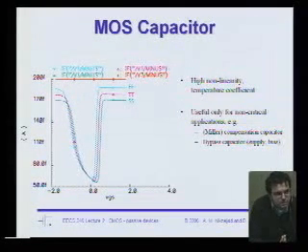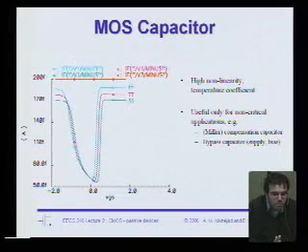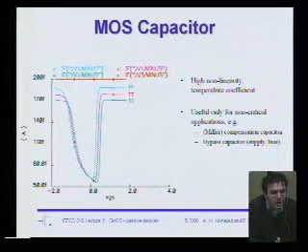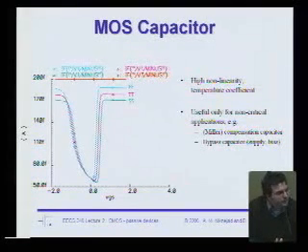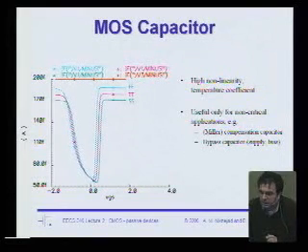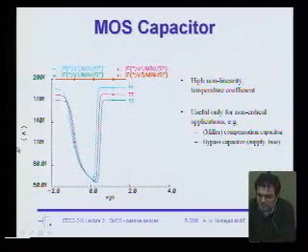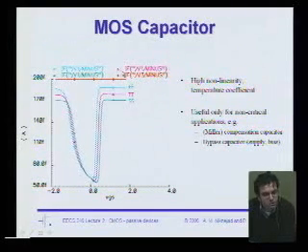Whenever you run a simulation, I call it run a sanity check first, because you can make so many mistakes. You can forget factors of pi. You might be interpreting the simulator wrong. So always put down something known, plot it. Okay, I know that this curve here should be 200 femtoamps, right? Because amps are farads here. And yes, it does hold, so my calculations were correct.